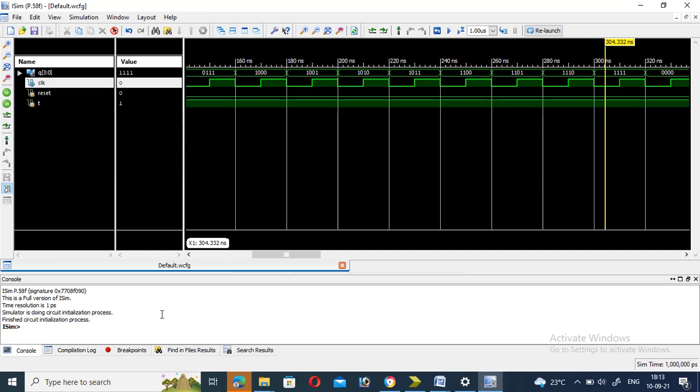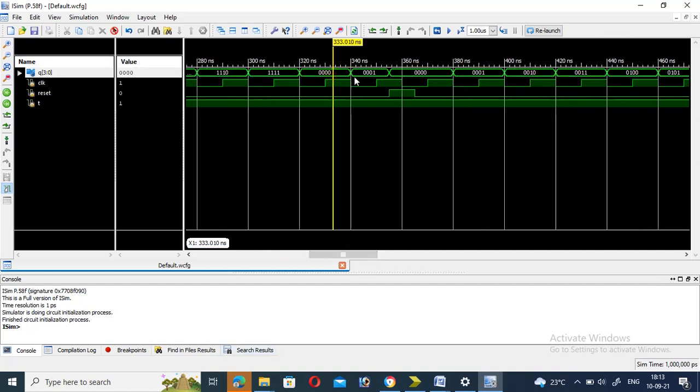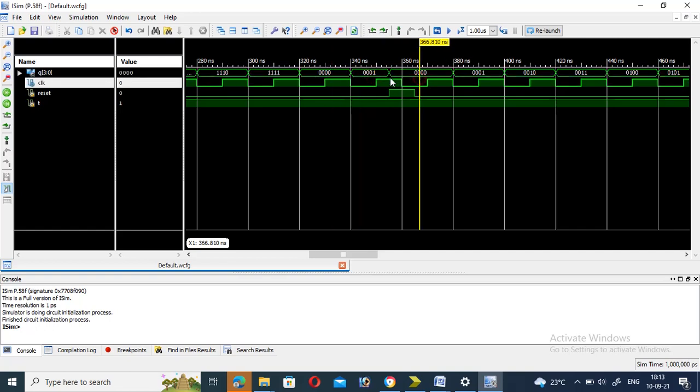That is nothing but a count from 0 to 15 states; it counted up to the end because of using 4 flip flops. Again what happens, it goes to the next 0th state and then the counting operation starts. Let us see here again 0 1. But you have to observe very carefully here: 0th state, then 1, after that 0. That means here after 1, 2 should come basically. After 1 we should go for the second state, right? But we are getting a 0.